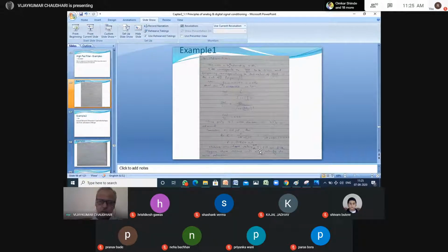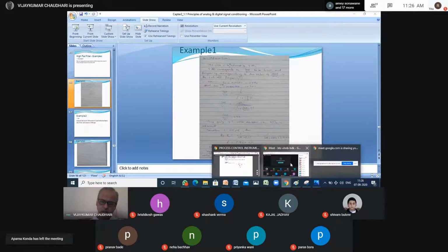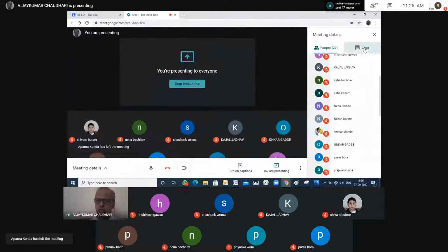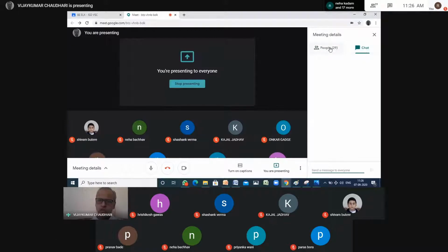Instead of choosing this standard value like this or this, I have to choose a potentiometer 0 to 10K and adjust this value each time to 7.957K. That's what I want to check. If with this value and this value I am getting V out upon V in as 0.03, then well and good, it is not necessary to use the potentiometer also. I can use this standard value. That's what I want to check. So what answer I'm getting? Still no answer.